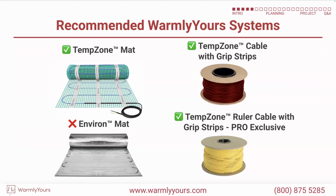So let's talk about the different systems. I kind of touched on Environ before. Environ is the fastest and easiest installation of any floor heating product that we sell because you simply roll it out on the floor and you put laminate on top of it. It's very, very simple. You don't have any cement, you don't have any thin set, you don't have any self-leveling, because Environ never attaches to anything. Nothing ever attaches to it, and it never touches the cement. So that's very important to keep in mind. That's why we brought up the difference between laminate, which uses Environ, and LVT, LVP, which doesn't use Environ.